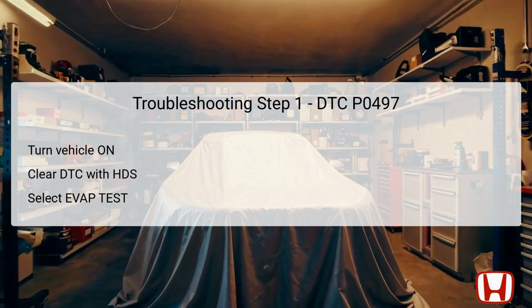The first step in troubleshooting DTC P0497 involves verifying the problem. Start by turning the vehicle to the on mode, which allows electronic systems to power up without starting the engine. Next, utilize the Honda Diagnostics System, HDS, to clear the DTC. After clearing the code, navigate to the EVAP test in the inspection menu and select the function test. This preliminary step helps confirm whether the issue persists or is intermittent. Should the result be okay, this points to a transient issue requiring closer inspection.